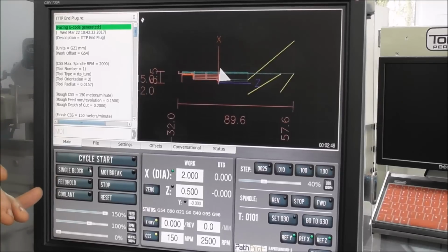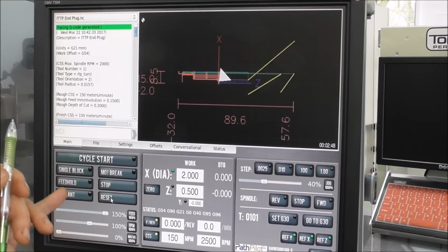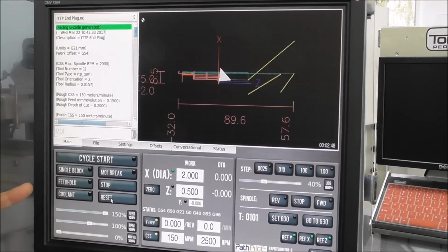Reset, start again, come back to that point, carry on. So with this wonderful facility of the maximum velocity slider, feed hold, stop and reset, you can work your way through the program very hesitantly, even if you're a very cautious, nervous person, and run your first part without risk of a crash.